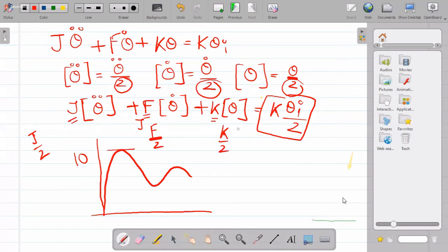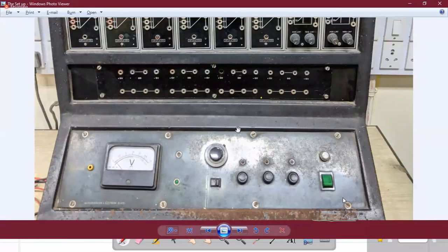So this is the basic principle of magnitude scaling, so that the amplitude of the output at no point should exceed this plus minus 10 volt range. This is the theme of the experiment that we should be covering in this semester. Previous to that, we have just given you the theory of what should be the analog simulation of a given differential equation and what you will expect as a response of the system. That I will discuss in the next concluding part, where I will be showing you the actual video clips of this experimental setup.